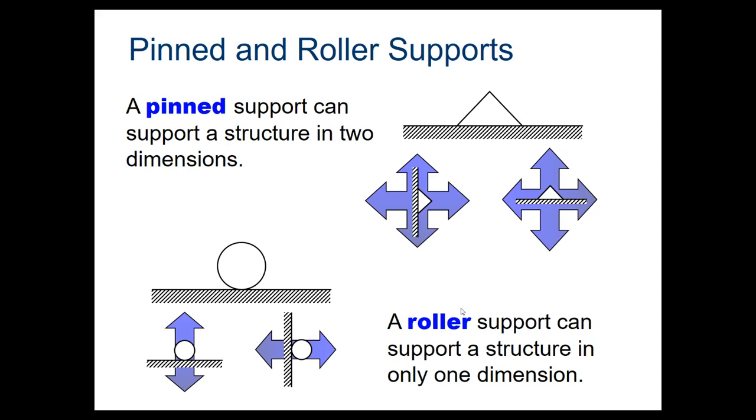So when we pin something down to the ground, think of it as almost like a lever. And that's our fulcrum of our lever. So we're keeping it from moving horizontally, we're keeping it from moving vertically, but we're not necessarily preventing it from rotating. Now, obviously, with the bridge, we aren't going to want it to rotate in some very special instances. So we really won't be using that rotational ability, but it is not being kept from rotating. So that is the thing to think about.